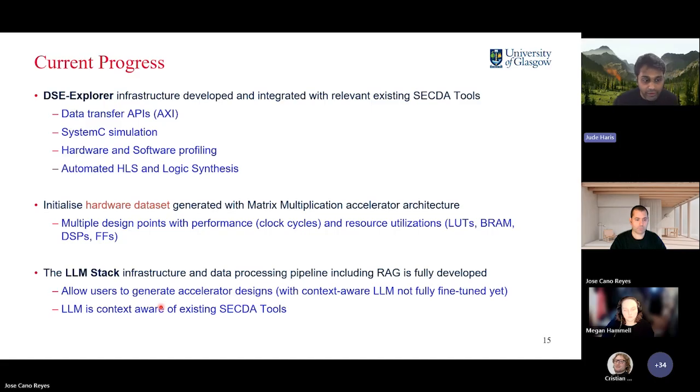Yeah. And moving on here, we will present the current progress and where we are in terms of all this implementation. So the DSE Explorer infrastructure that I mentioned before has been developed and integrated with relevant existing SECDA tools. This means that we have enabled data transfer protocols such as the AXI protocol, SystemC simulations completely integrated. We have hardware and software profiling tools, and also automated high-level synthesis and logic synthesis, all within the DSE Explorer tool.